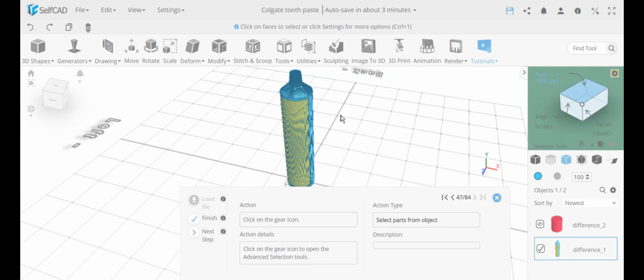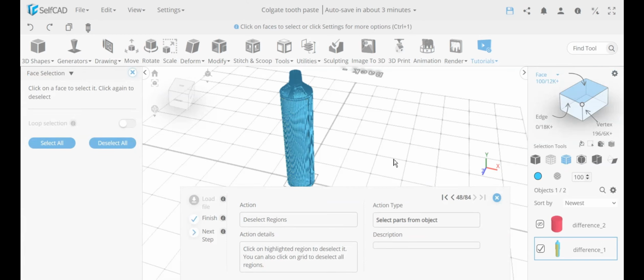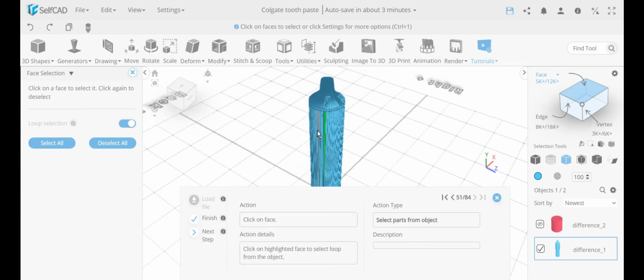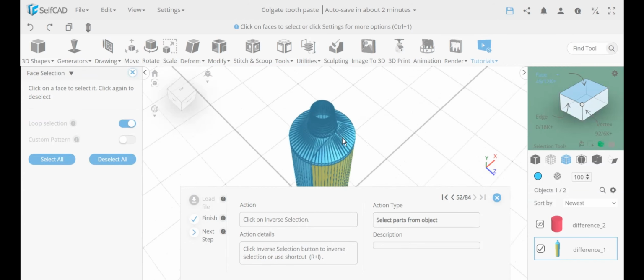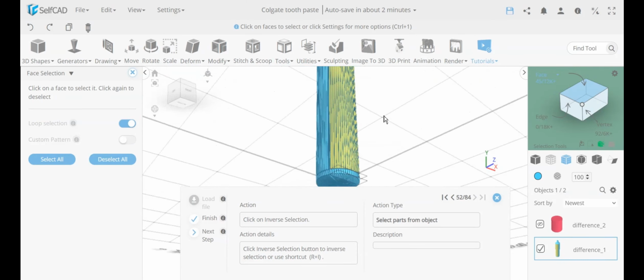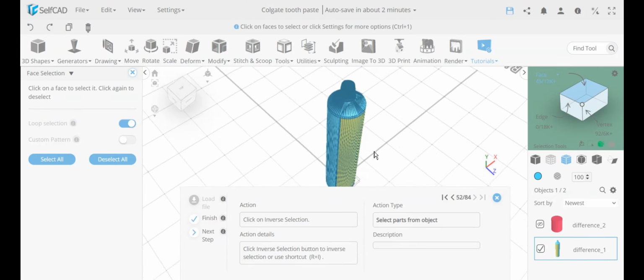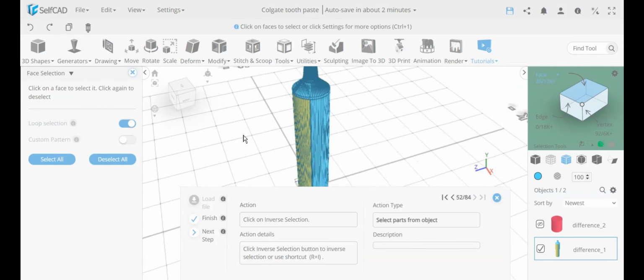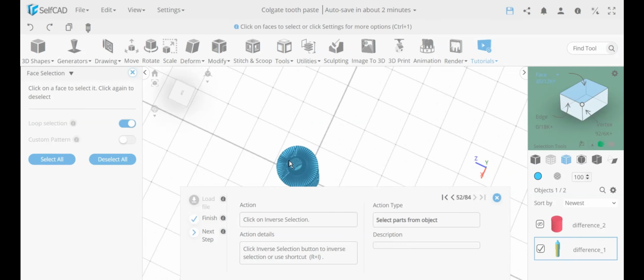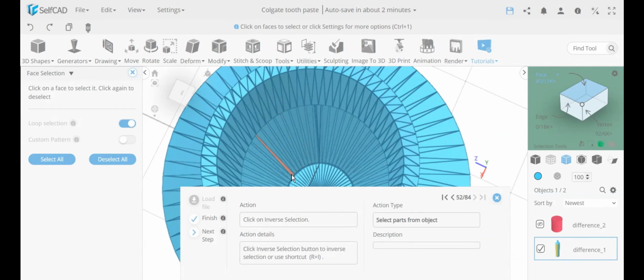And he's actually using over here advanced settings, and he's actually deselecting it. So you see, because now we don't want to select this, and he's going to make a custom selection using loop selection. But now we already have the proper cuts. You can see over here in the objects, let's see, so we select this. You can see over here, this was the cut, made it here, and it added this slice over here and the slice over here. Now there are many different ways you could have made these cuts, these slices, but the main thing I want to point out is not just how the designer made it, but I just want to point out the idea of making sure you don't have the inside faces selected. Now we selected only the outside.